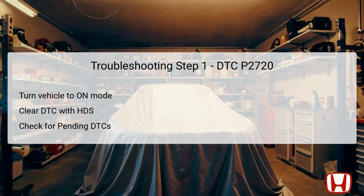In the first step of troubleshooting DTC P2720, the technician should turn the vehicle to the on mode, allowing the electrical systems to power up. After this, use the Honda Diagnostic System, or HDS, to clear any existing DTCs, which can reset the vehicle systems and help clarify whether the issue persists.